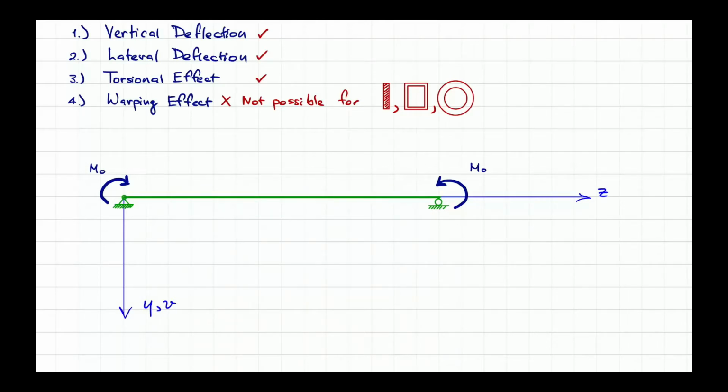If you imagine when we have just the constant bending moment diagram like this in comparison with other cases where you might have the bending moment diagram like this or like this, or for uniform load like this, other cases are not as critical as the case where we apply M0 on both sides. So this is the beauty of the techniques that is used for the beam stability analysis.